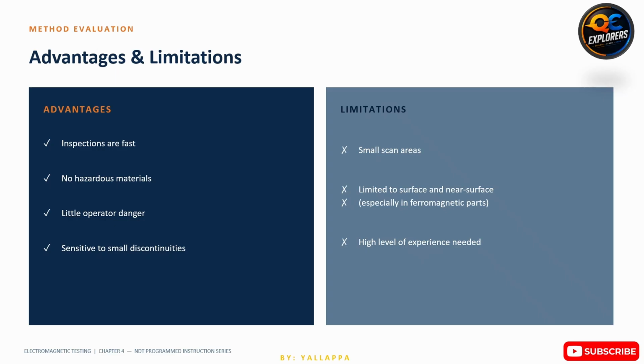Another advantage is that no hazardous chemicals or consumables are required. Unlike liquid penetrant testing, there are no developers or cleaners to dispose of, making eddy current testing cleaner and more environmentally friendly. Operator safety is also improved because the method does not use ionizing radiation or high-energy sources. In most situations, inspectors can perform examinations with minimal health risks.